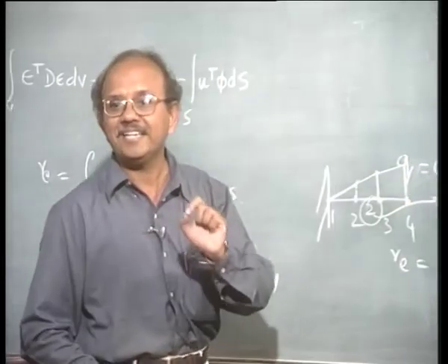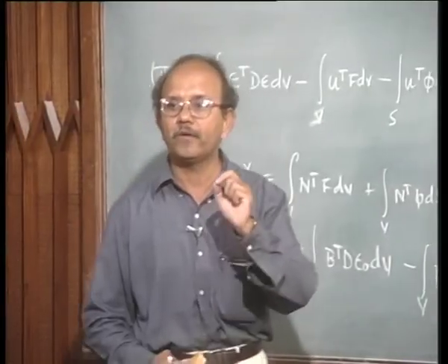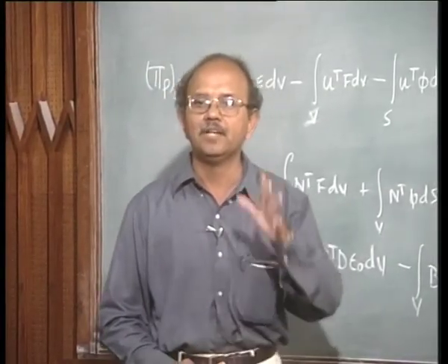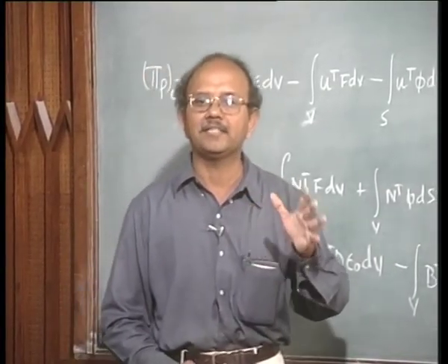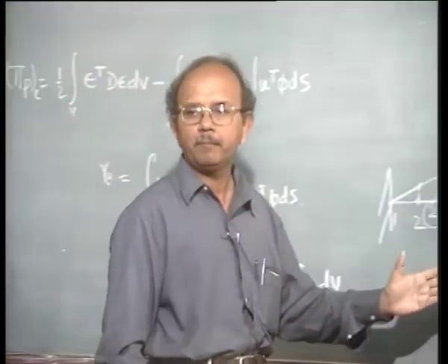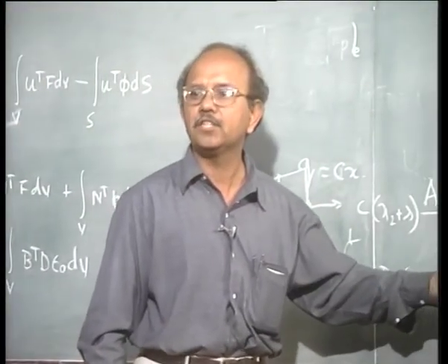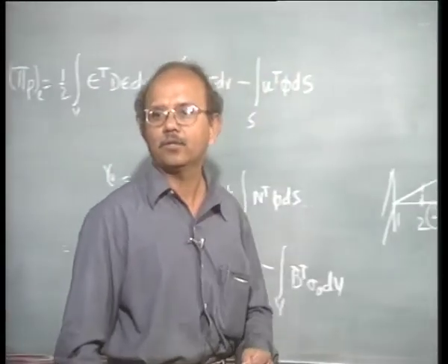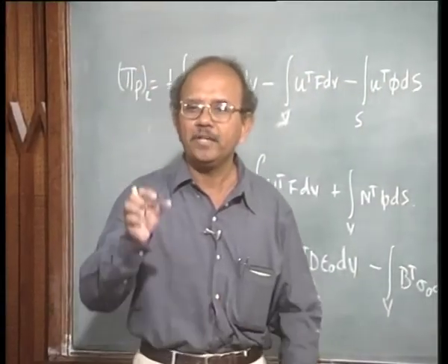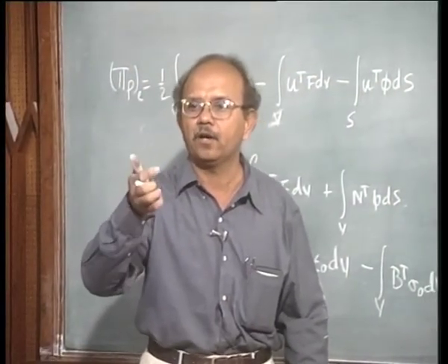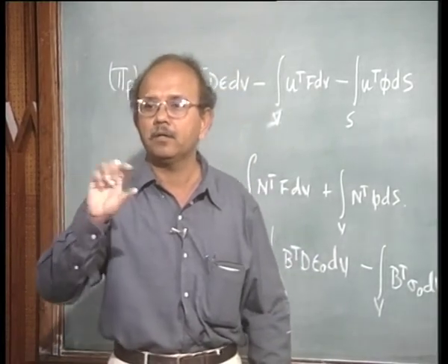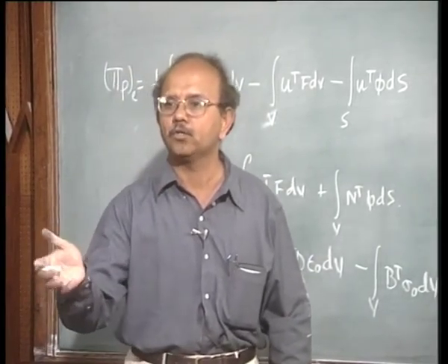Okay, now s is a local coordinate system. Always finite element has a local coordinate system. In the local coordinate system, I start s equal to 0 from the left hand end and then go to s equal to L on the right hand end. Hence there is going to be a transformation, if at all, from the global to local and local to global and so on.